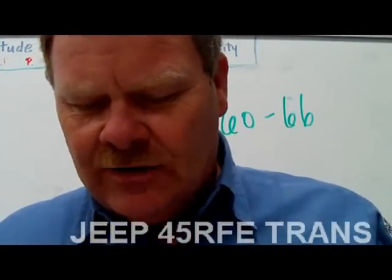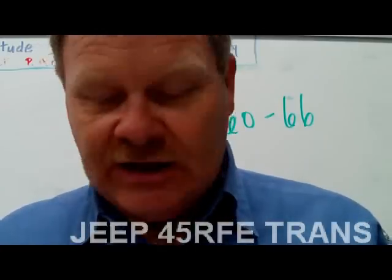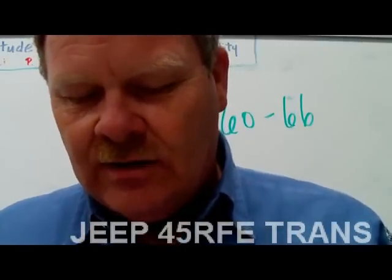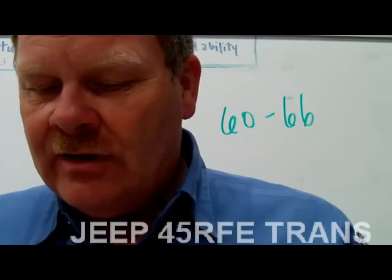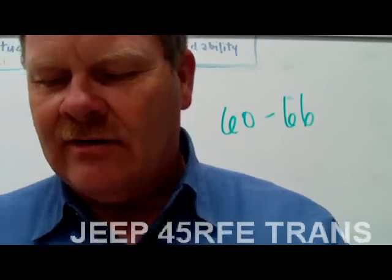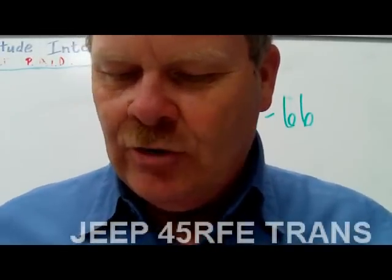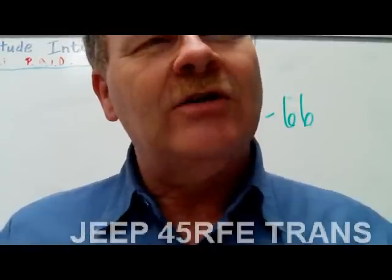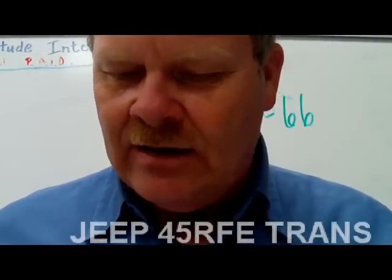All right, so you've got 3 planetary gear sets in this transmission, and that's one more than you're used to seeing in most transmissions nowadays. They provide a deeper low gear ratio, and this 4RFE doesn't need a separate overdrive unit. The unique characteristic of it is the alternate second gear ratio, or 2'. That 2' gear is enabled only during kickdown shifts, which is pretty cool. It allows a lower passing gear at highway speeds.